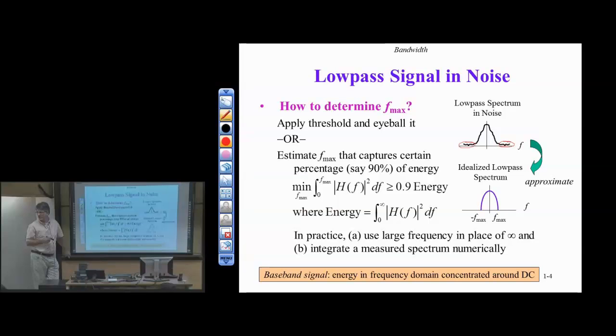Go ahead. So does the noise and the signal add up? Yeah, for the case of thermal noise, the answer is yes. It's just additive noise. It's independent of the signal that we're generating or transmitting. It's just there. It's just from the random motion of electrons. So it is additive in this particular case. Sometimes noise is not additive, and we'll talk about that a little bit later. But for most of the class, the noise will be additive. So here's a signal that we care about that's low frequency, and noise that's really at all frequencies.